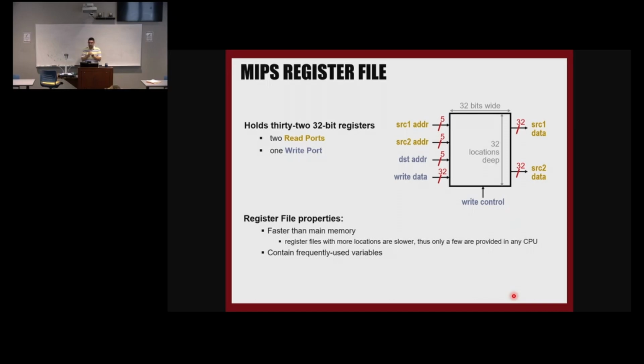Because that's like the 32 is 2 to the 5th. Yes, you only need that many to figure it out. So we have 32 cells. 32 is 2 to the 5th, and then we need 5 wires, 5 lines to address 32 memory cells, and that would be enough.